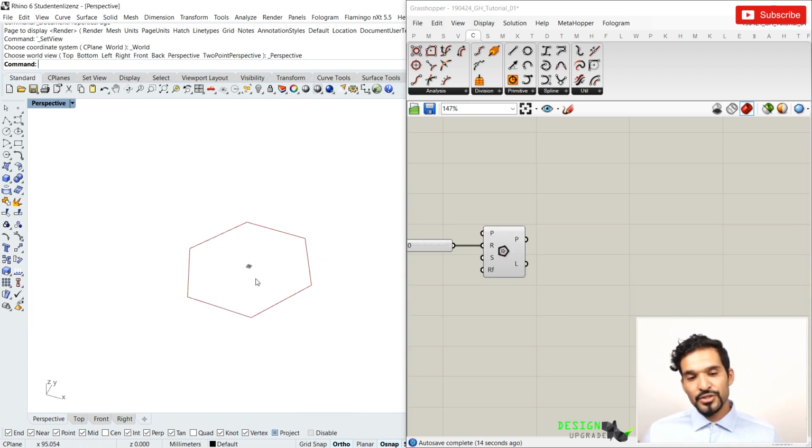The next thing I want to do is I want to not take this geometry to Loft, but I want to make it a bit more interesting. And the way that I want to do this is I want to take the line going like this, but then I want to stop here and go into the centroid of my geometry and make a connection to this point here. So I get rid of these 2 segments and actually do a new line that goes from this point to this point and this point to that point.